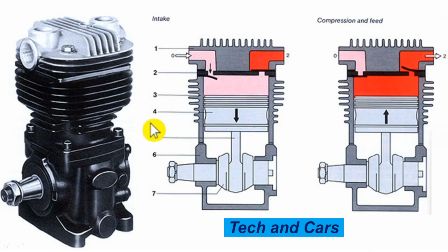And if you want to prolong the service life of your air compressor, always follow a scheduled maintenance plan. Compressors, like any air dryer, when they work, they need to have a filtered air supply, and that air filter has to be regularly replaced, and it has to be cleaned if it is filled with some sort of dirt. Now, these are some of the things that you can do in order to prolong the service life of your air compressor.